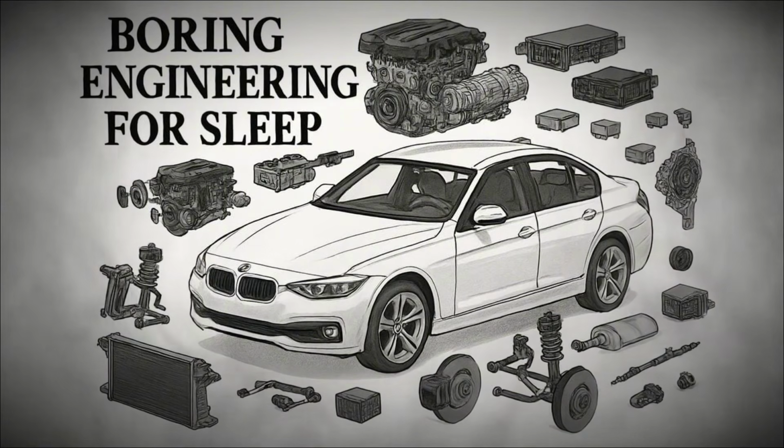Combustion engines come in several configurations depending on how the cylinders are arranged. Inline engines place all cylinders in a single row, which makes them simple and compact. V engines place cylinders in two angled banks, creating a V shape that allows for more cylinders in a shorter length. Flat engines, sometimes called boxer engines, place the cylinders horizontally opposite each other for low vibration and a low center of gravity.